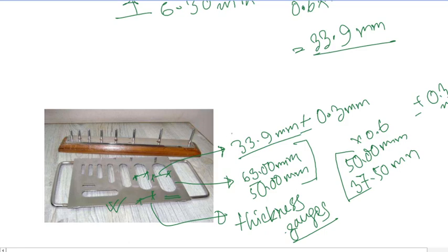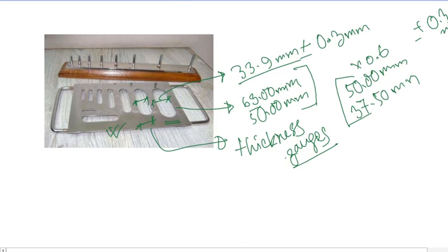So what will be our effort? We will be trying to pass the particles through this opening. Whenever we have particles retaining on 50 millimeter and passing through 63 millimeter after sieve analysis, we will try to pass them through this opening in any manner.